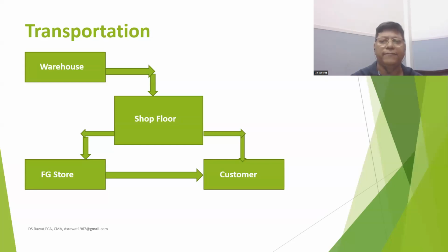This is a huge saving, but we have to see what its impact is. First, it eliminates the inventory, and second, it reduces the movement and reduces the manpower cost. And third, there is a wastage during the transportation because some parts get damaged. So this all can be eliminated by this single step. Therefore, JIT is also one of the techniques of lean manufacturing.